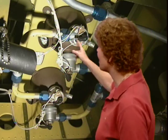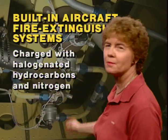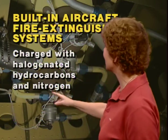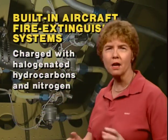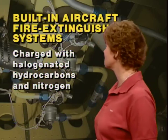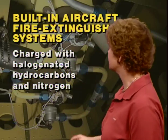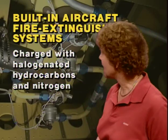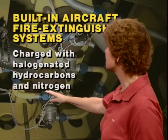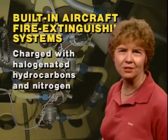Now, what are these bottles normally charged with? Typically, they would be charged with halogenated hydrocarbons, that's halon, and with nitrogen. They would not be charged with carbon dioxide or sodium bicarbonate. The halogenated hydrocarbons, the halon, is the fire extinguishing agent, and the nitrogen is the propellant that gets it out there and distributed through the engine.